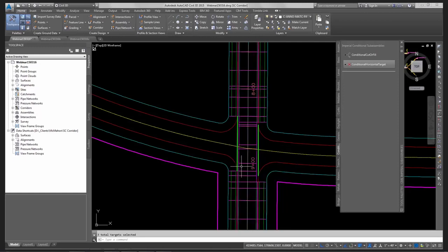A little bit simpler. I don't want to say it's simpler than the intersection wizard, but if you have to build your intersection manually, I typically take the primary road, drop my curb like I did here, and then tie in the secondary corridor into here.